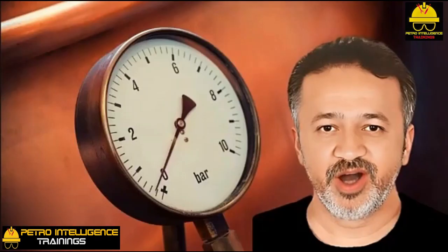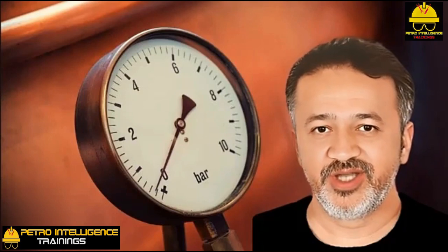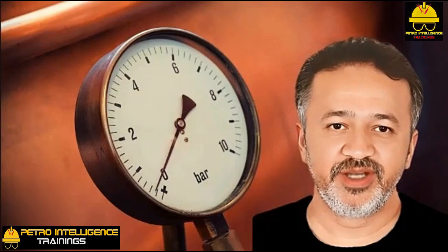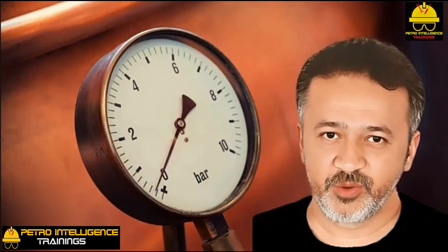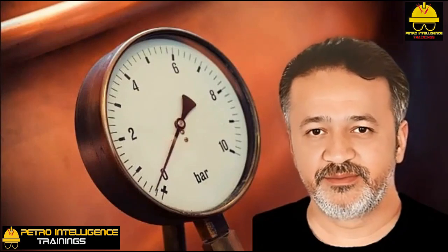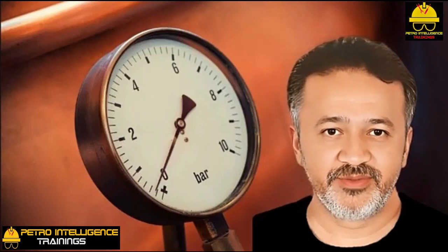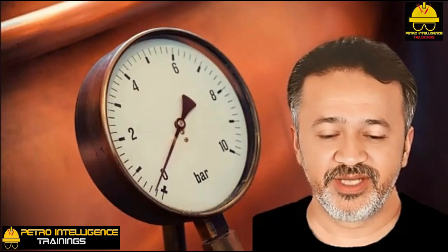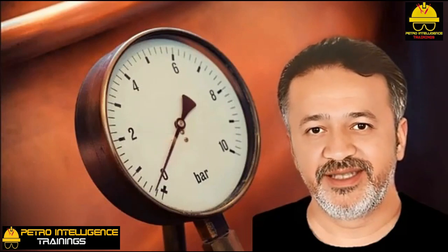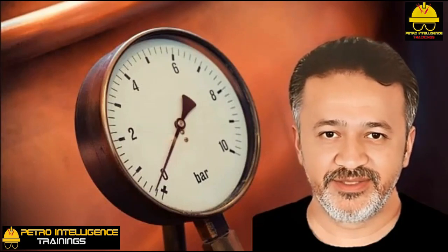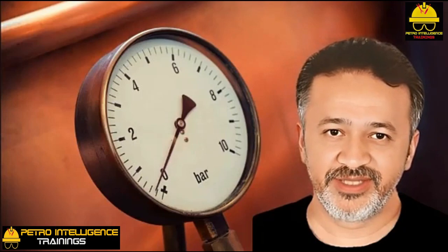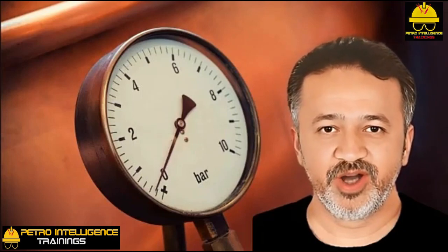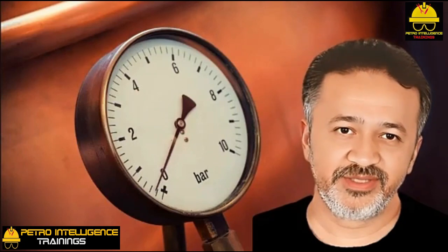Effects of temperature on level. The gauge glass will normally be somewhat colder than the process vessel as a result of ambient heat losses. An exception to this would be a refrigerated process. For every 100 degrees Fahrenheit decrease in the gauge glass temperature or level troll temperature, the specific gravity of the liquid in the glass increases by 5%. This rule of thumb is typical for hydrocarbons only. Aqueous or water-based fluids are totally different.